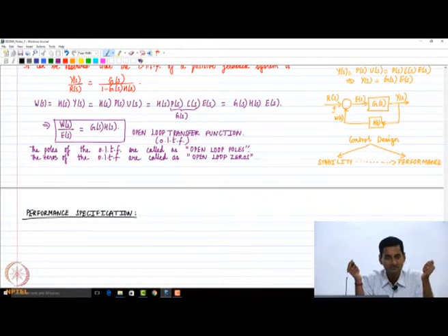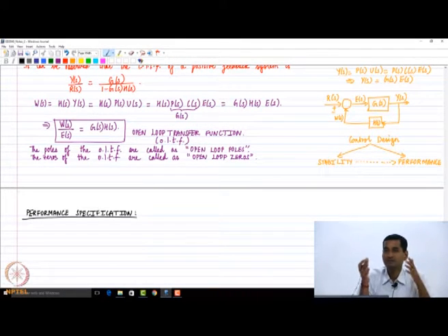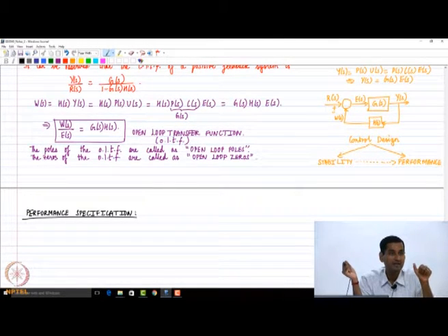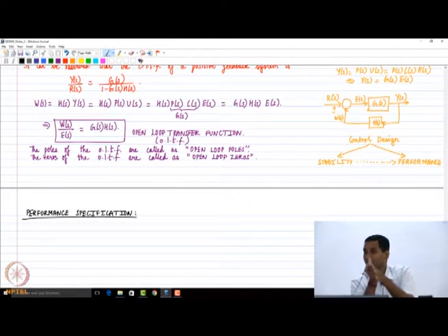How fast it will go? Very good. Let's say I come into this room in summer. Let's say the room temperature is 38 degrees Celsius. I want it to go to 25. I look at each controller, and then I set my reference as 25 degrees Celsius. I may evaluate how fast it will go to 25. That's one. Very good. Then, how accurately it can maintain it around 25. How fast it can settle around 25 and how close will it remain to 25.